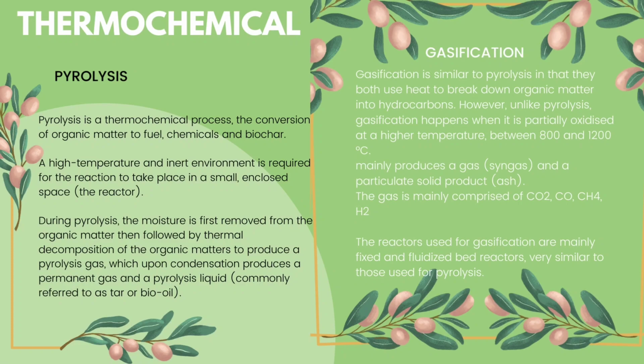The gas is mainly comprised of carbon dioxide, carbon monoxide, methane, a very small fraction of hydrogen, and a very small fraction of tar. There are a variety of potential applications of the gasification particulate, such as biodiesel production and a catalyst for tar cracking. The reactors used for gasification are mainly fixed and fluidized bed reactors, which are very similar to those used for pyrolysis.